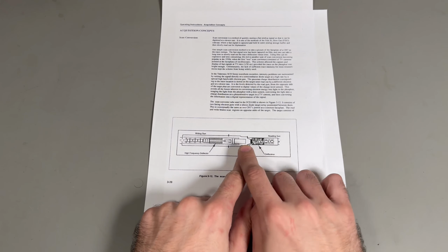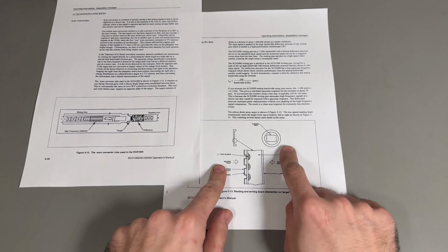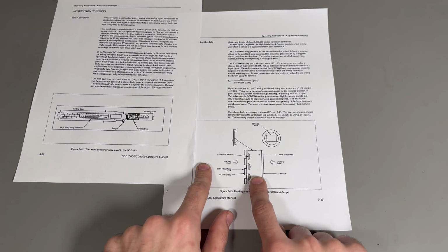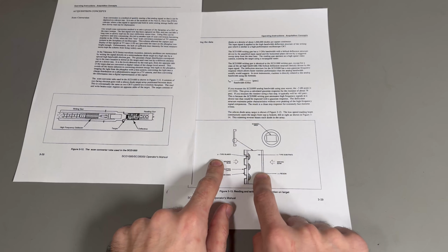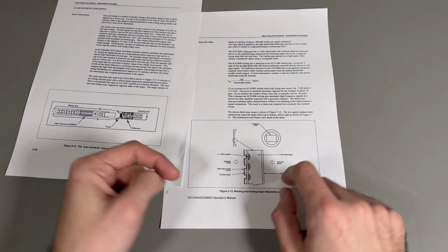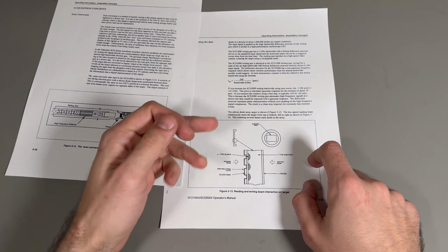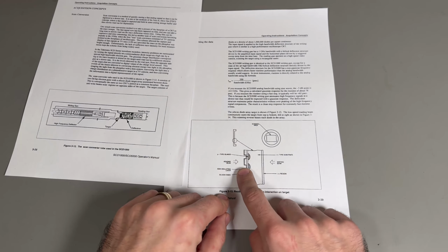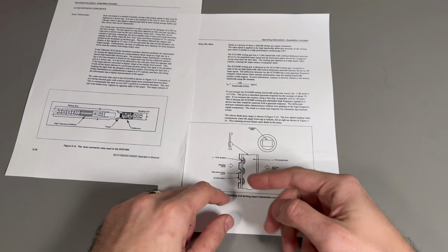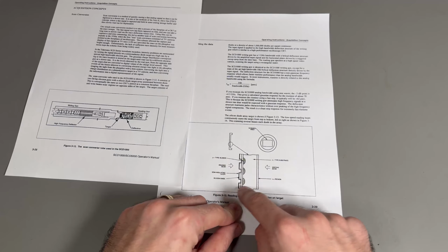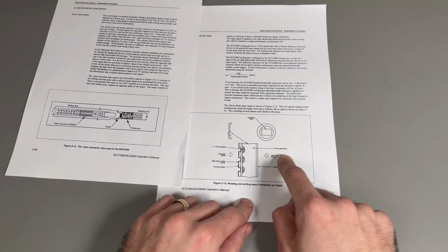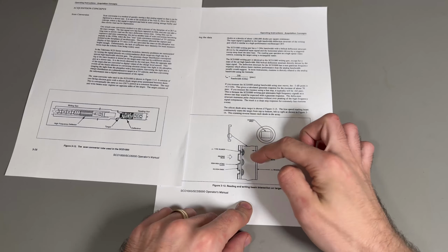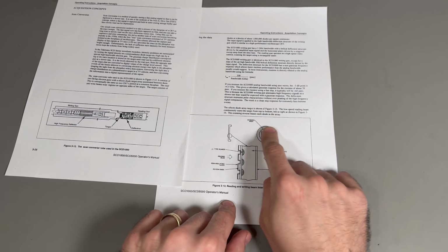So how this thing works is that you have a very fast CRT scope tube here that blasts a target area made out of about 1 million diodes per square centimeter, and they look like this. It's an N-type substrate with P-type islands. The write gun scans the signal across the surface here. And from the other side, once a signal has been captured, there's a read gun that scans across that matrix in a zigzag pattern and measures the beam current.